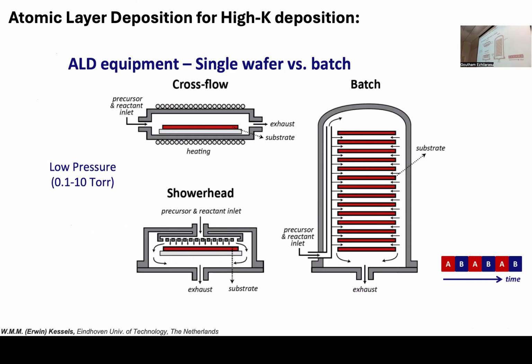So when you do ALD, you want to cover everything, including the space here. But in order to cover the region here with ALD material, the gas has to go in all the way here, and then the product has to come all the way back, right? However, if these things are very narrow, then the transport tends to saturate, so it doesn't go all the way inside. So you can end up depositing only here and not all the way inside. So even though it is conformal, it is still limited by mass transport. If you have very, very fine features, sometimes the gas just doesn't go all the way down, because the gas has to go and the product has to come out, right? This is an issue in CVD as well. So it is still mass transport limited.